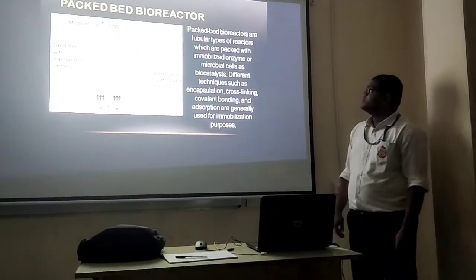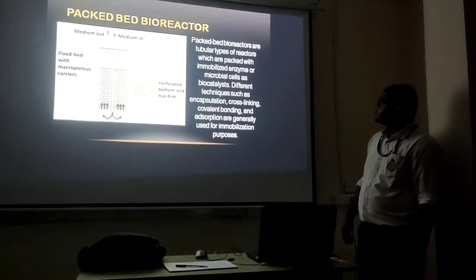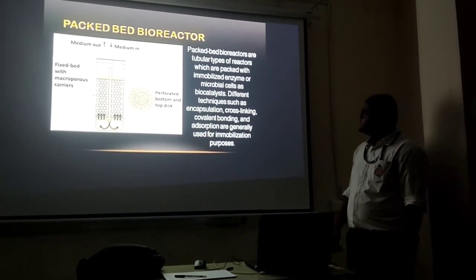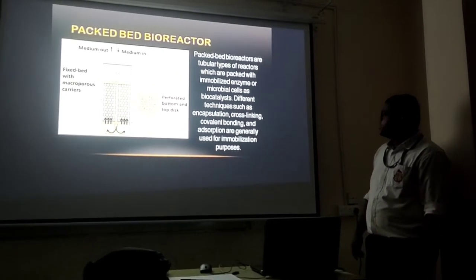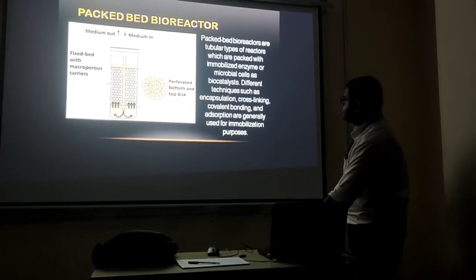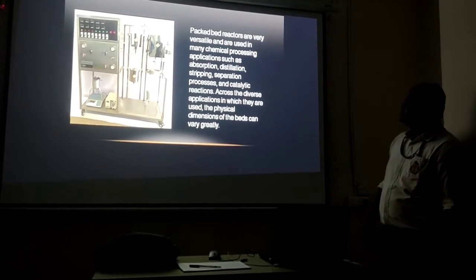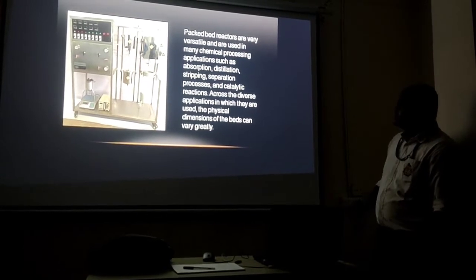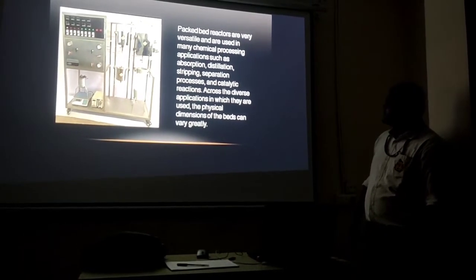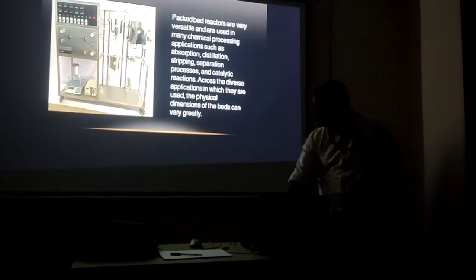Coming to the next one, the packed bed bioreactor. Packed bed bioreactors are a tubular system of reactions packed with immobilized enzyme or microbial cells as catalysts. Different techniques such as encapsulation, cross-linking, covalent bonding, and adsorption are generally used for the immobilization process. Packed bed bioreactors are very versatile and are used in many chemical process applications such as absorption, distillation, stripping, separation processes, and catalytic reactions. Across the diverse applications in which they are used, the physical dimensions of the beds can vary greatly.